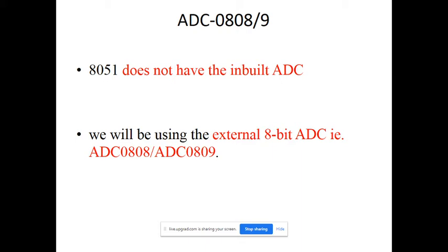According to that, suppose your room temperature is more. In that situation, you must start the fan. Suppose your room temperature is very low. In that case, it will harm the crops. To avoid that, we want to turn on the heater. Suppose moisture in the soil is less. At that time, you want to turn on the pump. Suppose moisture in the soil is much more. At that time you must stop the pump. All these are controlling actions to start and stop the devices.